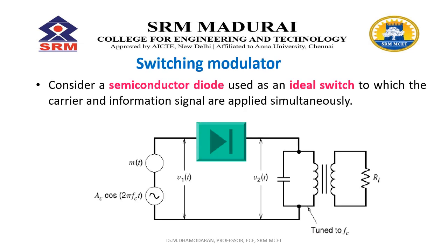Another type of modulation is the switching modulator. By using a semiconductor diode, we can use it for this transmission. Here the diode acts as a switch to which the carrier and the information signals are applied simultaneously.